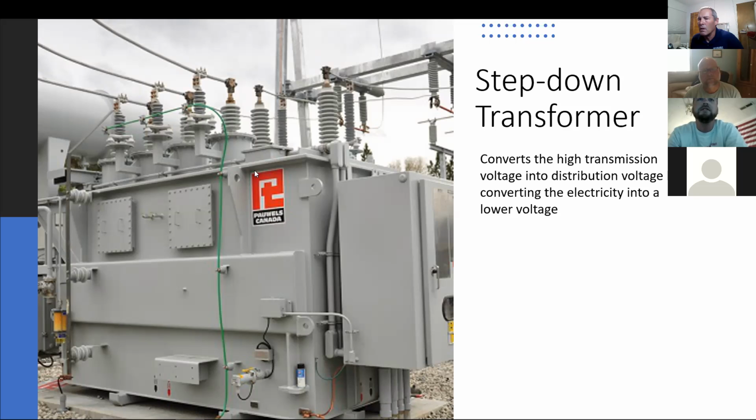Is the one with the green line the ground, isn't it? No, the green line is actually a light. These are lights. So you have the transmission input voltage here, then you have the output voltage. Right after that, they put a lightning arrestor to help protect the transformer. So that's a lightning arrestor right there. And that's the ground that goes down to ground. Good picture.